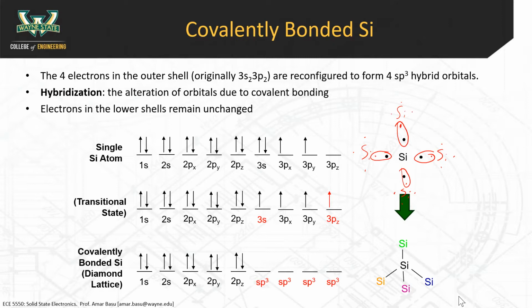that tetrahedral bonding, the bonding orbital, so the fact that these two electrons are shared between the two silicon atoms, when you have a pair of electrons forming a covalent bond, that covalent bond is represented by a hybrid orbital. All right? So each silicon atom in the middle is bonded to 4 other silicon atoms covalently, and so there are 4 corresponding sp3 hybrid orbitals. And how many electrons are going to be in there? You guess? 8. Yeah, they're all going to be filled, right?